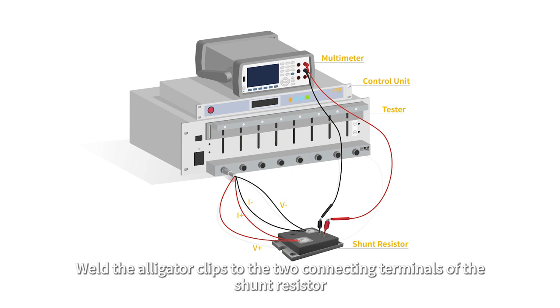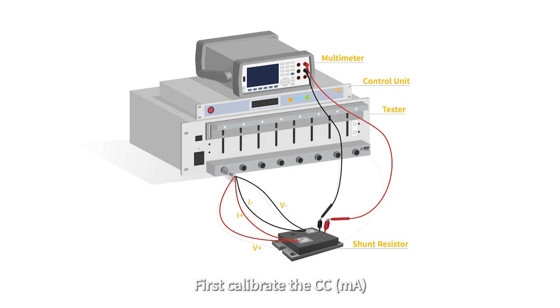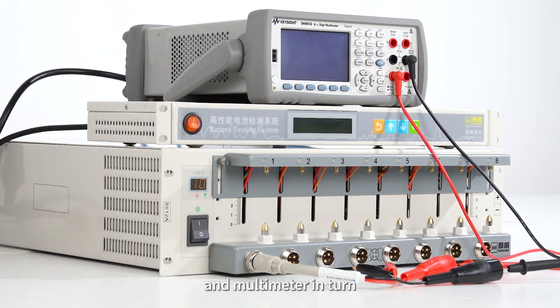Weld the alligator clips to the two connecting terminals of the shunt resistor and connect them to the positive and negative probes of the multimeter. First, calibrate the CC milliampere, the specific wiring as shown in the figure. After powering on the device, start the tester, control unit, and multimeter in turn.